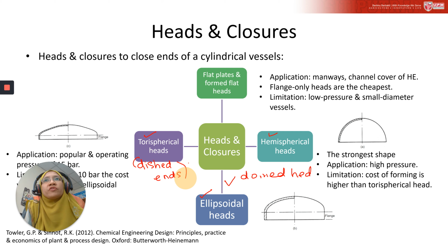Flat plates are generally used for manways and channel covers for heat exchangers. There is also a type which is flange only heads, where the flat end is known as a flange only head. The flange only heads are the cheapest.